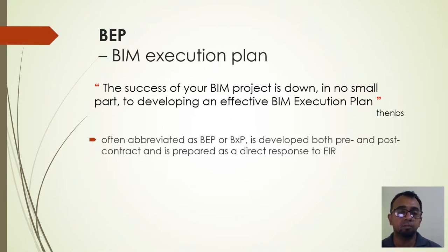The BIM execution plan is prepared consciously for a project by considering both the project program and the parties involved, or likely parties involved if it is at a pre-contract stage, and mapping those to the EIR.